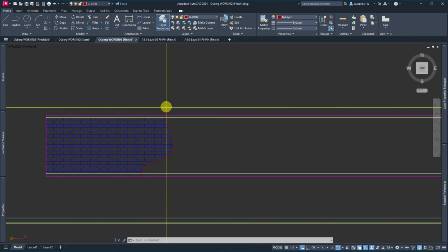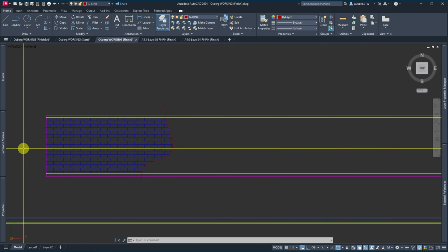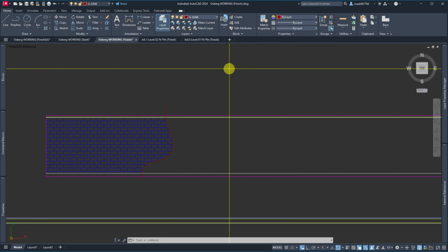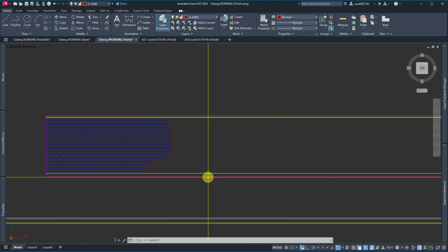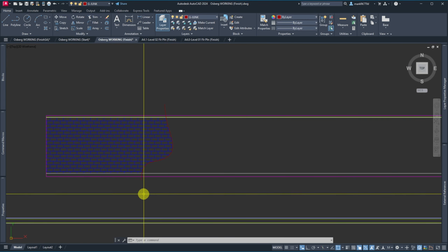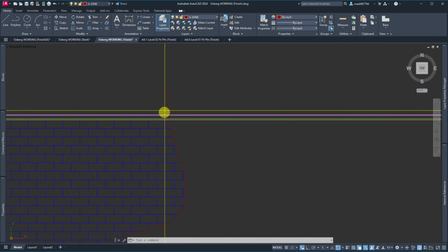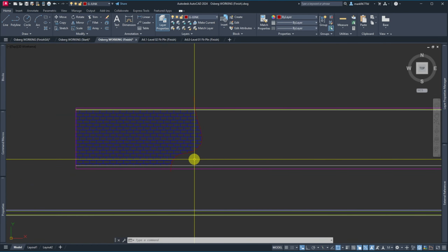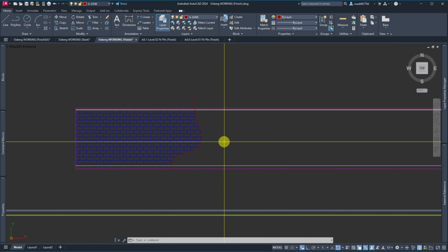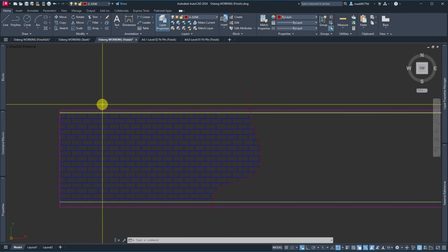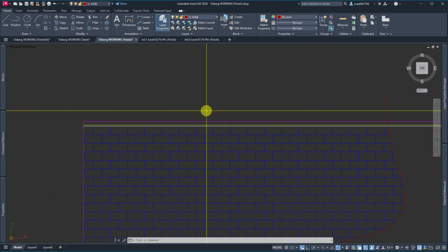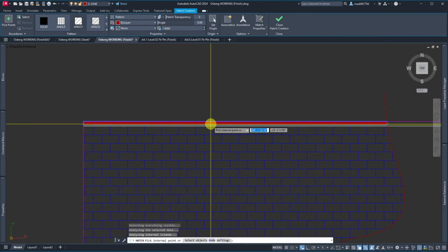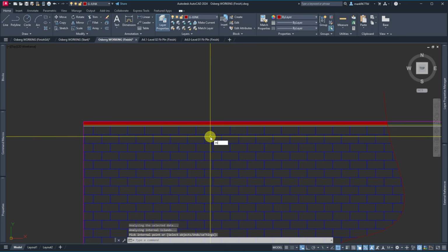I leave these here because if I have to lengthen a roof, cut it off, or change the roof height because I made a mistake, these lines are still hanging out here. And I just run them long so I can account for any changes. And then if you want to, you can hatch in there because that's going to be shingle.